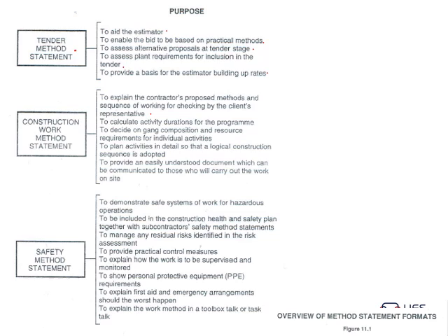If you stop, you can't stop at certain points in a slab like that, because the structural integrity of a slab like that is compromised if you've got a joint or cold joint at a certain place. So for instance, if you want to have a cold joint over your columns, so that if there's a joint and there's movement, both sides of the slabs, you can see there's two different slabs actually supported by the column underneath. So that's the type of rationale that you need to think of when you're preparing a method statement.